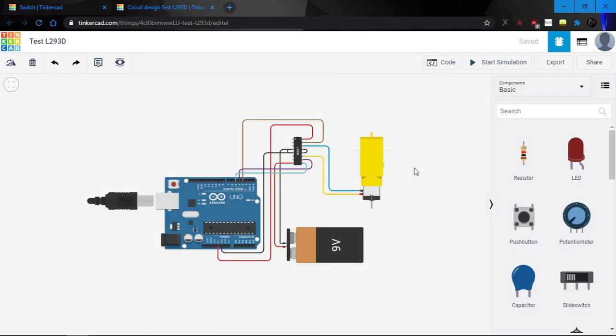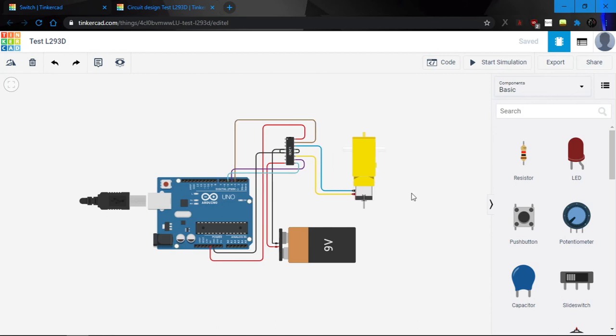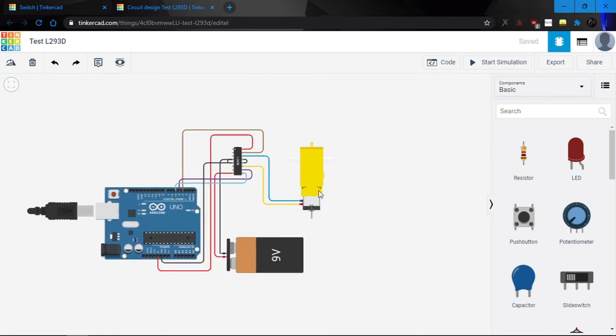Lastly, you will learn how to use a motor driver. When we use a DC motor, it only has 2 pins, which control the direction. If we only use these 2 pins directly with Arduino, we cannot control the speed using coding, and the speed will 100% depend on the power of the power source. That's the first issue.